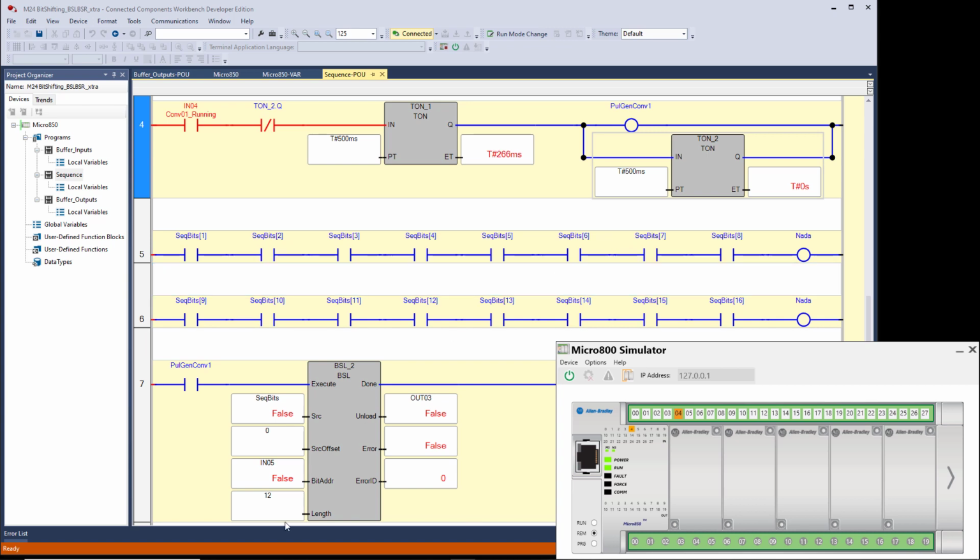So remember, we have a length of 12 down here. That means that the bits are going to get pushed into sequence bits 1, and when they get pushed out of 12, they go into the O zone. They don't use 13, 14, 15, 16, and all the way up to 100. Remember, sequence bits, that's an array of 100 elements, 1 through 100. We're only using a piece or a section of that array of Boolean data types in memory.